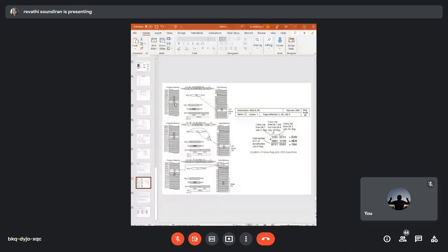Okay, now execution of this instruction copies the contents of R4 of the bank 0 to the accumulator. So therefore, after the execution, the accumulator will have the value D7. Okay, and since the move operation is a data transfer, flags will not be affected. That we have already seen. Okay, data move.